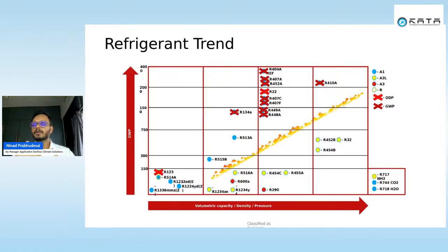That is why there are a lot of new developments going on in the products, let's say compressors or electronic expansion valves, where they are qualifying these components for higher temperature ranges. Most of the demand I can see for higher temperature is with R600A or R1234ZE. We will see in the upcoming slides how the compressor can benefit with these gases. So for the heat pump market, I think these are the two refrigerants.